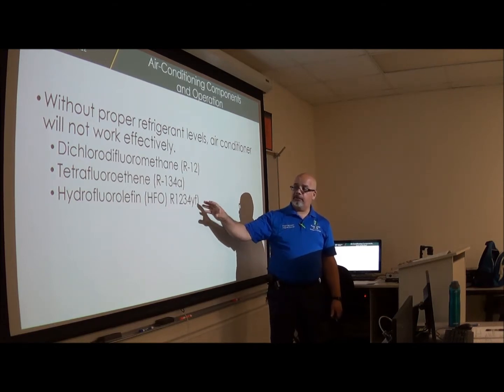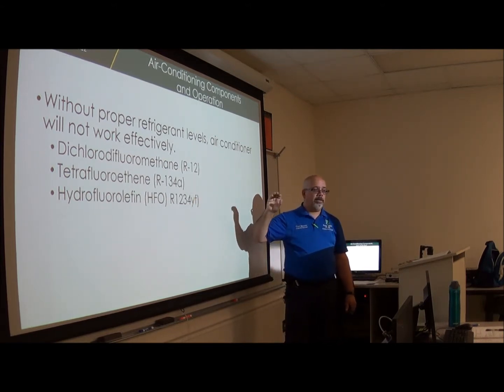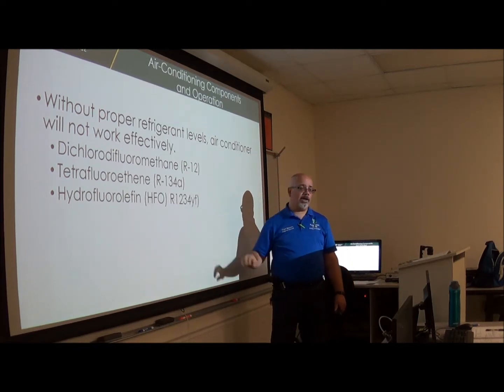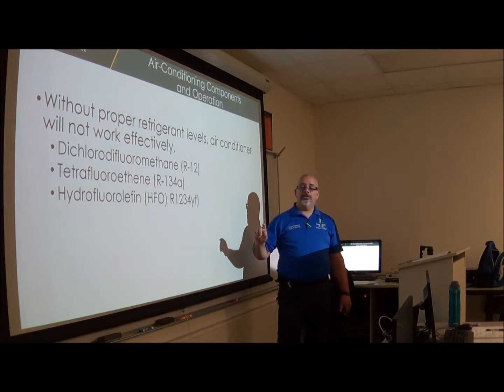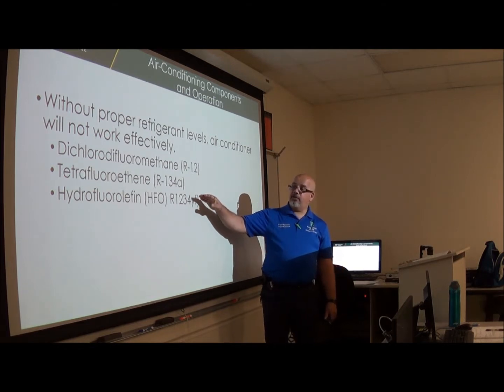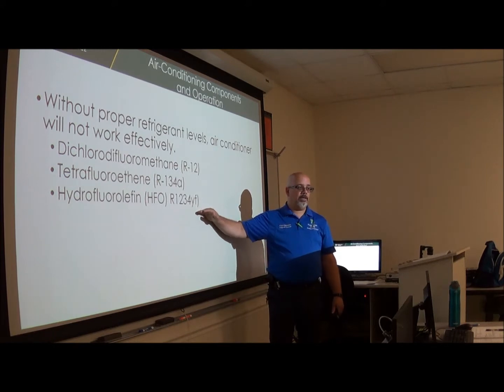R1234YF has a different coupling, and you can't use the R12 or the 134A gauges there, because R1234YF is highly flammable. The pressures are also higher, so we can't use anything we used for the other two. So the 1234 is for the newer cars, they only use 1234.